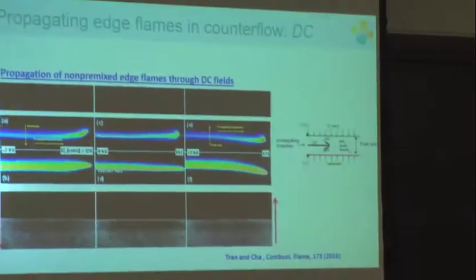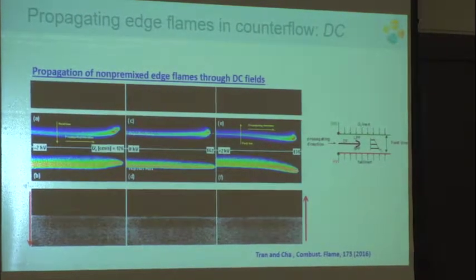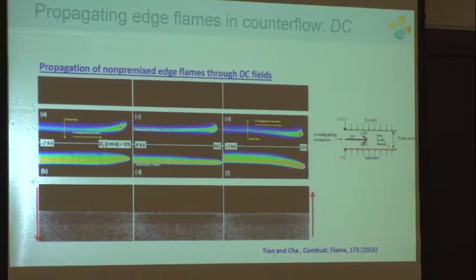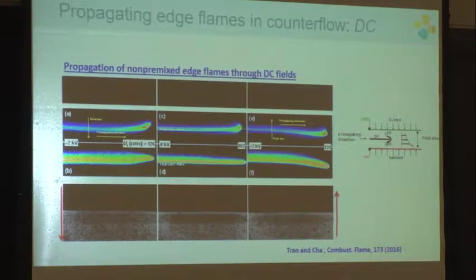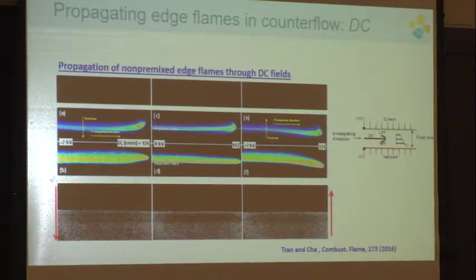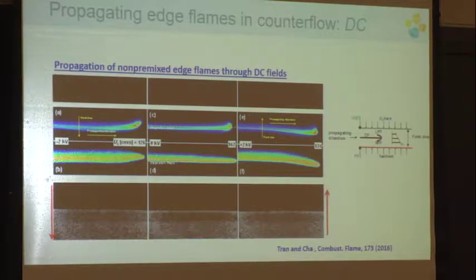And the question, really, in this kind of electrical field effect on flame, is not just the interest in the flame shape changing in the wind. Rather, combustion people try to ask the question: does the electrical field really change the flame speed?